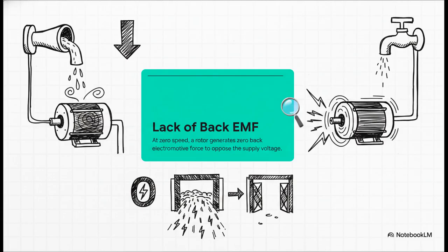It's a nice equilibrium. But at the exact moment of startup, when the motor is at 0 speed, it generates absolutely zero back EMF to oppose the supply voltage. There's no pushback. It's basically a wide open door for electricity to rush right in.